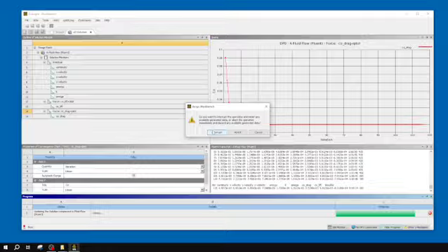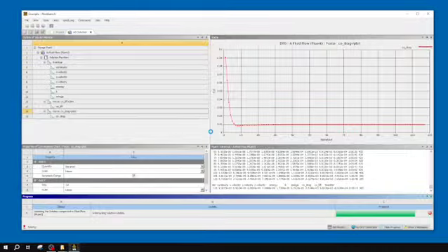it'll also throw out all the data it's already calculated. If I interrupt it, it'll continue its calculation till it finishes the next iteration and then safely exit out. So if you wanted to calculate more later, you can come back in and start that back up. So I much prefer interrupting. The only time I'd suggest aborting is if something goes wrong and the data is unusable, then you can abort. But for really any practical purposes, again, I suggest interrupting.